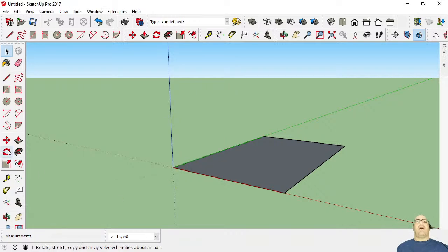So if I, for example, go to draw another line, I can do that, and before I click anything, you'll see that my length is showing 0.52. If I type into there 5M and hit return, that line is now exactly 5 meters long. Right?